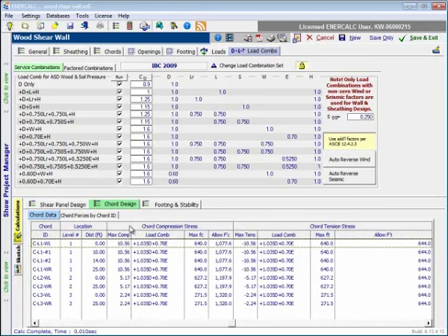The chord compression stress category reports the maximum compressive force that's experienced by the named stud, the load combination that's responsible for generating that compressive force, the maximum compressive stress that's experienced by the named stud, and the maximum allowable compressive stress. And then the chord tension stress category reports all the same information, but from the tensile perspective. So the maximum tensile force is reported, the load combination that's responsible for it, the maximum applied tensile stress on the member, and the allowable tensile stress.